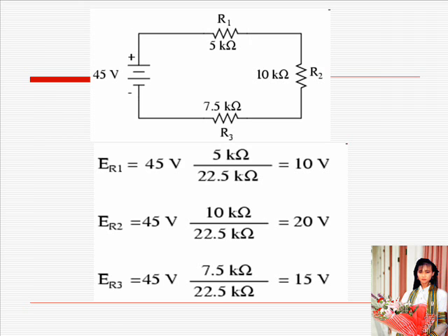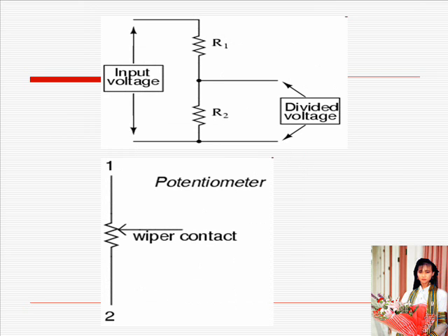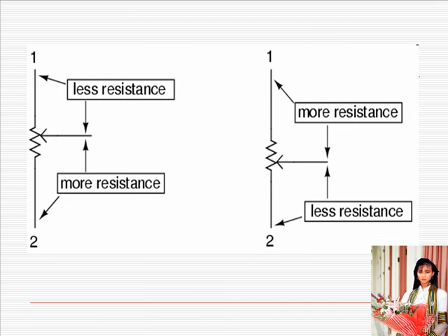One device frequently used as a voltage dividing component is the potentiometer, which is a resistor with a movable element positioned by a manual knob or lever. The movable element, typically called a wiper, makes contact with a resistive strip of material, commonly called the slide wire. The wiper contact is the left-facing arrow symbol drawn in the middle of the vertical resistor element.